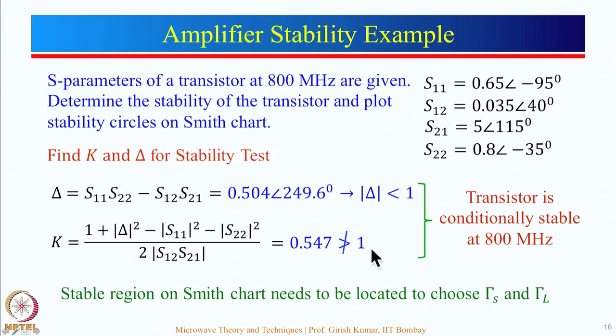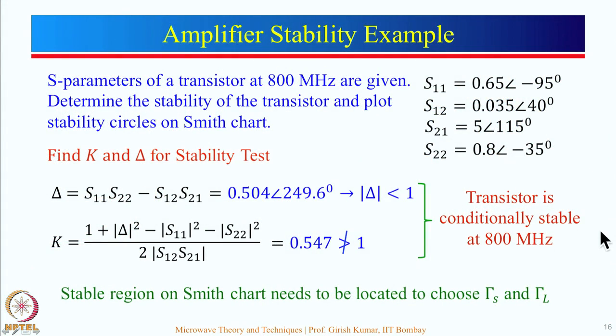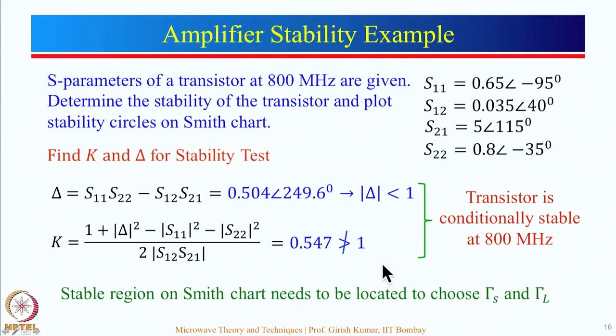But instead of saying amplifier is unstable, we generally use a little different term. We call it transistor is conditionally stable. What it really means is that for certain cases, this particular transistor may be stable, and if you satisfy those conditions, then this transistor can be used as an amplifier. But when I discuss about the oscillator, the same thing I am going to say that this particular transistor is unstable. So, please do not mix up.